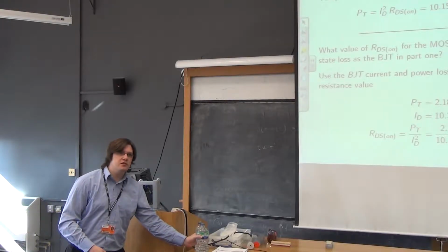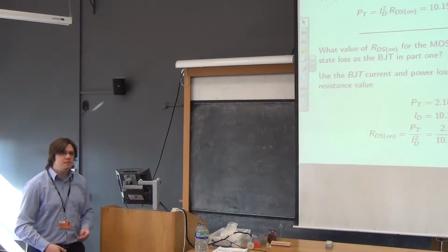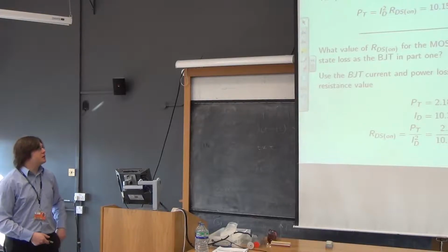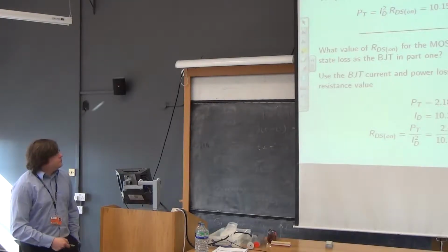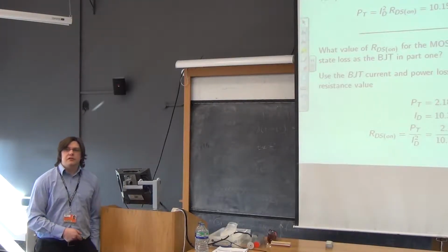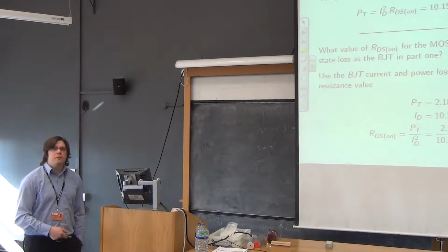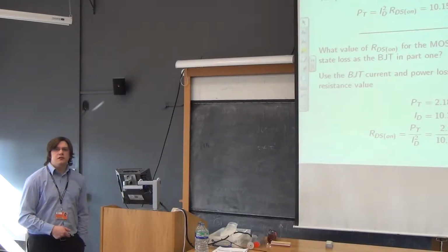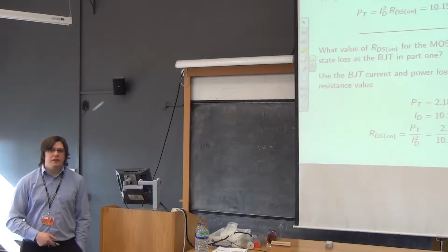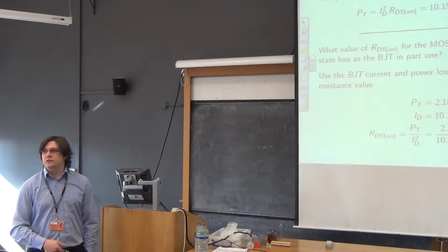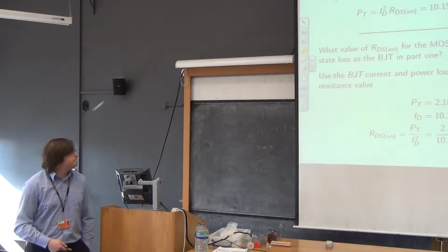Obviously, we'd like to minimise the transistor power dissipation and maximise the load power dissipation. Or at the very least, we'd like to make the circuit as efficient as possible by making the load power significantly greater than the transistor power, and the end point of significantly greater is no transistor losses at all.